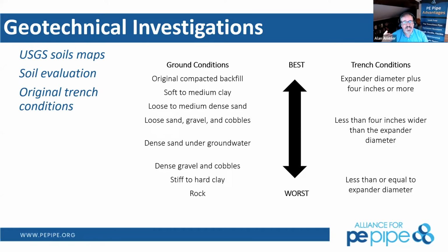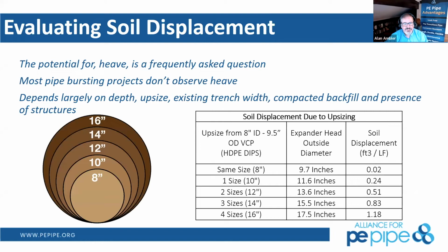That concept over the years has often been hard for Department of Transportations to understand when we're moving through and they're worried about the compaction of the backfill on top of it. But in the 1960s, Terzaghi, a very well-known geotechnical engineer, came up with that soil arching theory, directly from his noggin and his brain. So in here, that brings us to soil displacement.